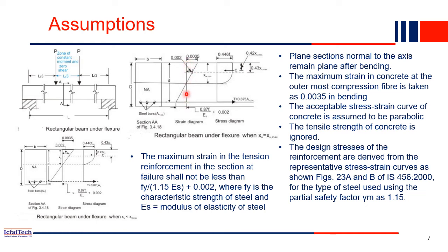So this is the zero stress, zero strain axis. Top fiber is subjected to compression, so from here 0 it goes in the positive direction. Whereas the bottom fiber is subjected to tension, meaning negative stress, negative strain, so that's why we put it on the negative side. Now you understood, right? Top fiber is positive, whereas bottom fiber goes negative. And this is the actual strain diagram. If you connect both, this is the strain diagram.